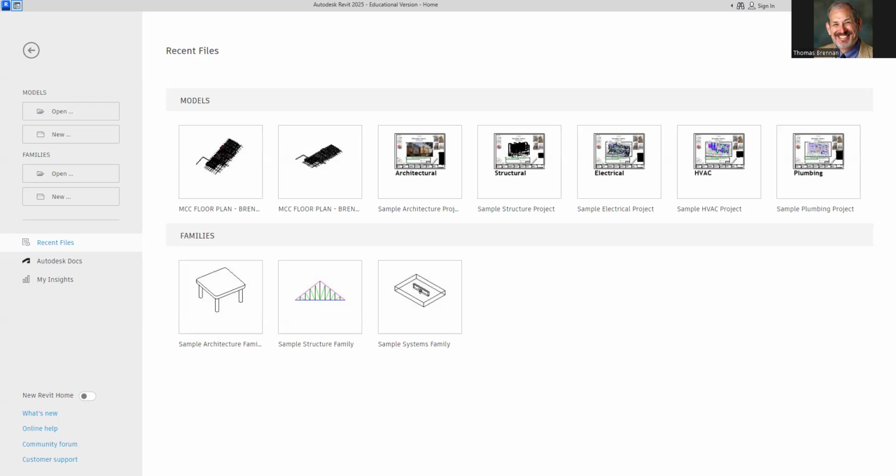So when I was doing the floor, I didn't have the greenhouse built yet, that section. So is there a way I could go back in to add a floor just to that portion? Or do I have to redo the entire floor? Oh, no. You just go into level 1 and double click on the floor. When you double click on the floor, the purple polyline will show back up, and you just edit it.